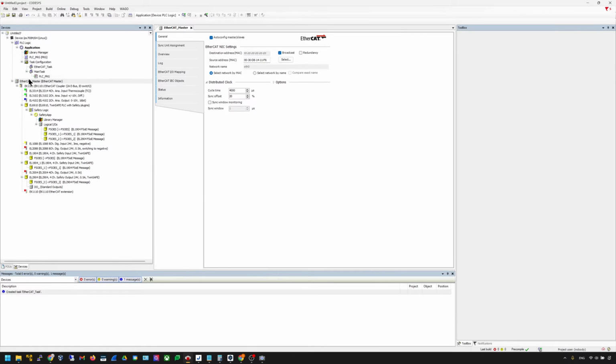Okay, so now I have my EtherCAT master. I have an EL6910, so in this case I need to configure this one. The first one, I will click the FSoE inside the logic IOs. Here I have 3 items, because, as I told you in the slide before, I installed 3 safety modules in my EtherCAT network, EtherCAT couplers. So you'll see there are 3 FSoE modules in here.